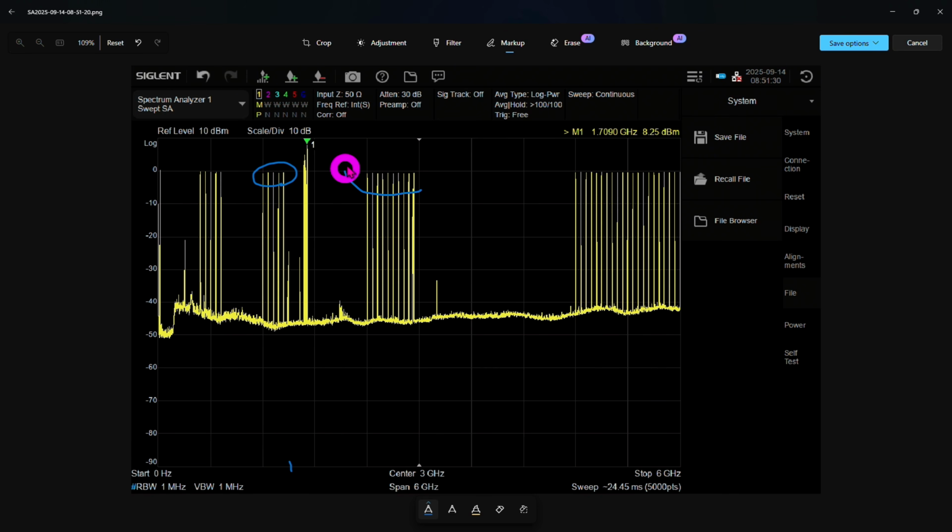Now, if you look at this section, this is just this part multiplied by 2. So no wonder that this section is also working, because that's just a doubler range of the VCO. As long as the VCO is locked within that range, the double frequency seems to also be working. And then this section, which is even wider, is also the double again. That's why they keep getting wider and wider, because you're doubling the frequency, so the range in absolute value is increasing. So double over here, double over here. So these are all really the same signal, just multiplied.